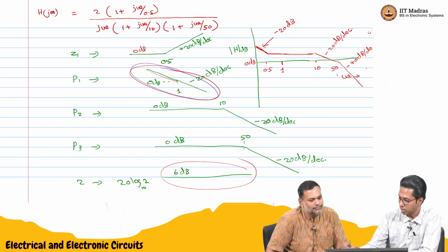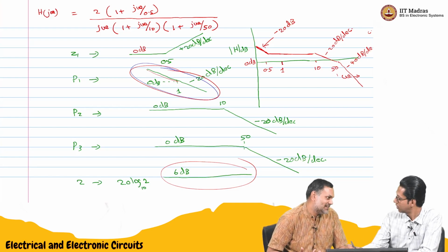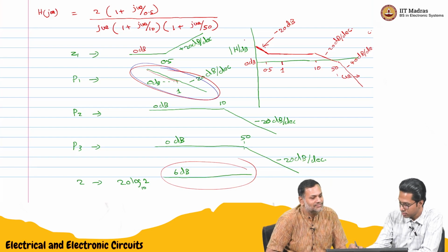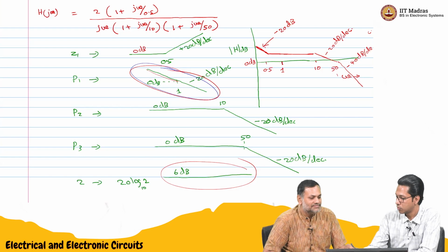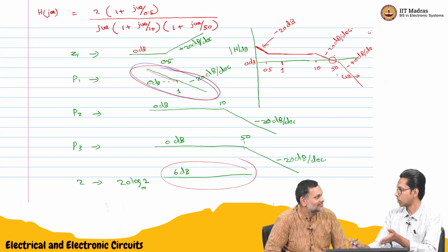So actually, if we have a log plot, then we can even calculate these values and put down what it is. So from there go to minus 20 dB. From there it will be flat. Again, draw at minus 20 dB. So this crossing point, etc., will automatically happen.